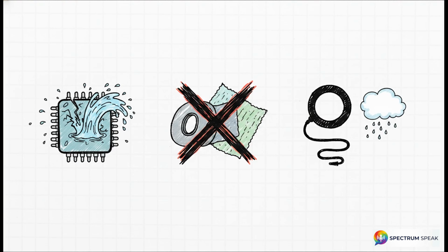Let's lock in the 3 main takeaways. Number 1, never forget the water hammer. ESD is a rapid, destructive equalization of potential that will physically shatter your components. Number 2, respect the materials. Charge generation is governed by the triboelectric series, so keep synthetics, cheap plastics, and regular tape completely off your bench. And number 3, ANSI standard workstation setups are not optional. Ground yourself constantly and keep that lab humidity at or above 40%.